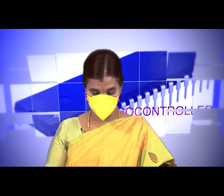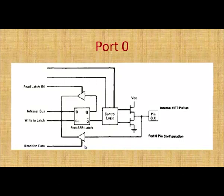Now we will discuss each port's circuit and how it operates. This is the port 0 circuit. This kind of circuit is used for port 0.0 to port 0.7, so all 8 lines have the same circuit. Here one D latch is connected along with the control circuit with 2 NMOS. Then there are 2 read pins available: one is connected from the pin, and another one from the latch.